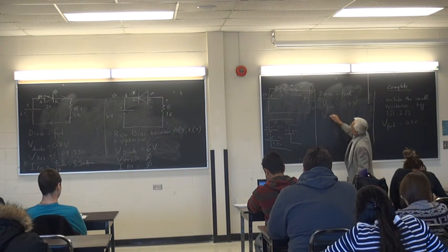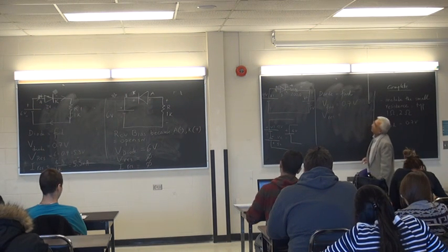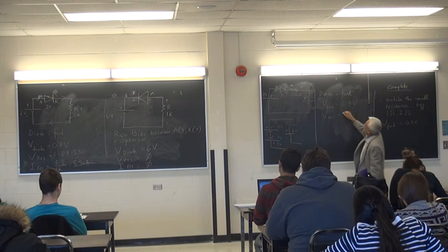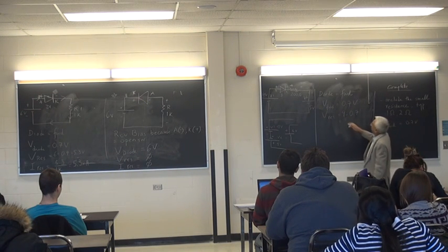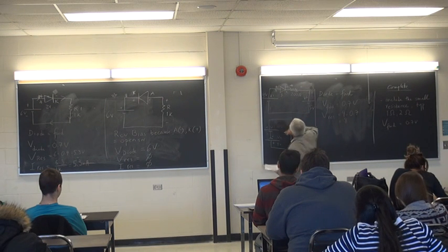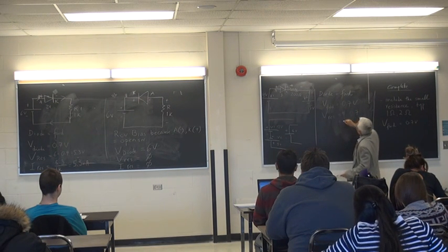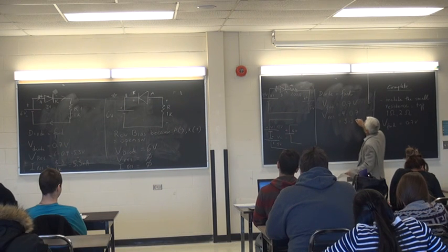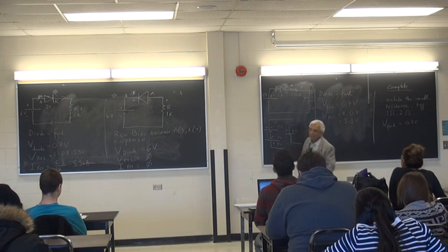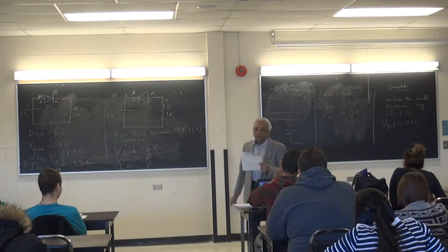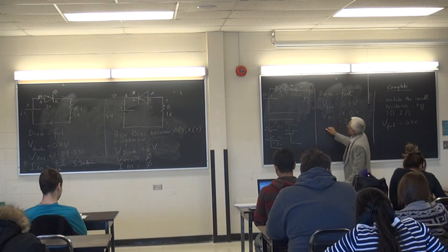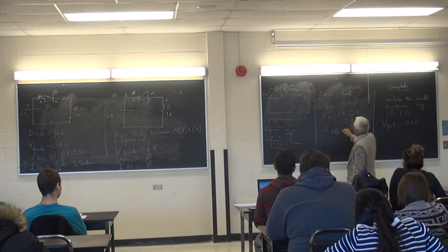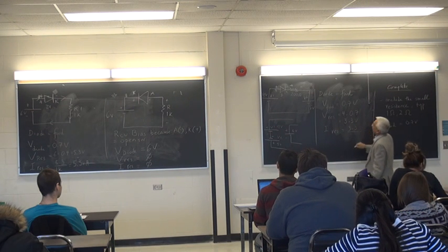How much at the resistor? 9 minus 0.7, 8 point. Sorry, 4. Thank you. 4 minus 0.7, 3.3. Why 4? Because 9 minus 5 became 4. Okay, so that's my voltage at the resistor, and then the current in the circuit, 3.3 over 200.